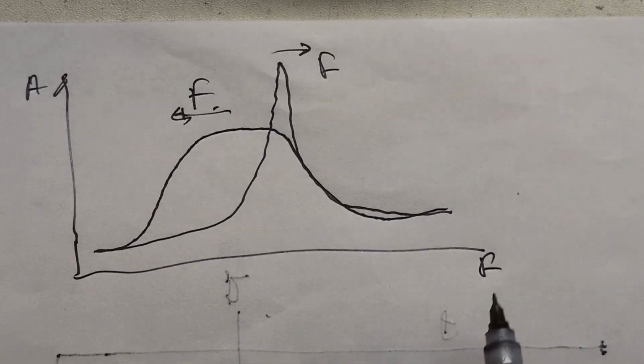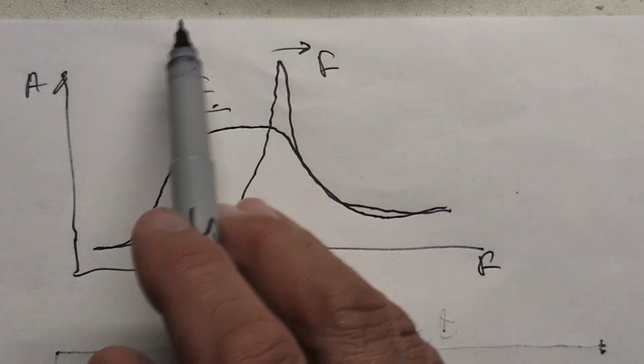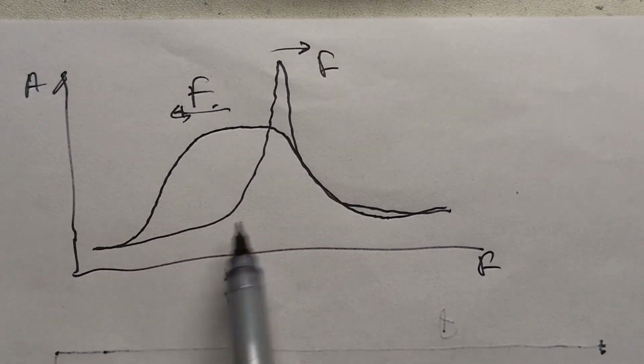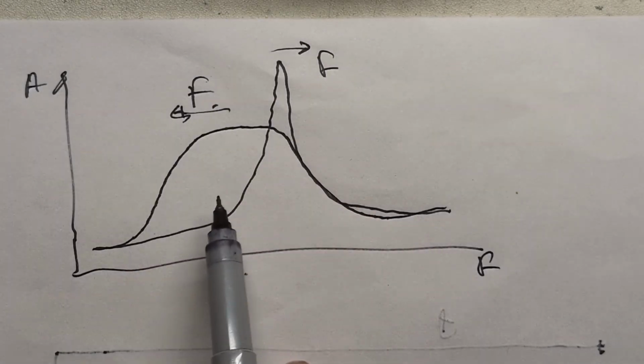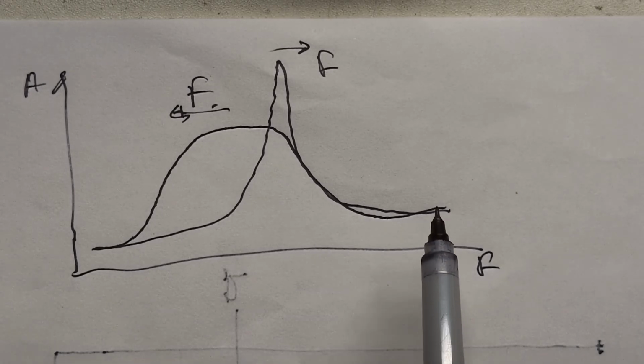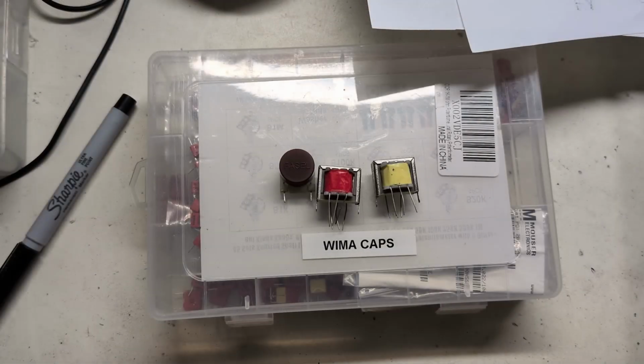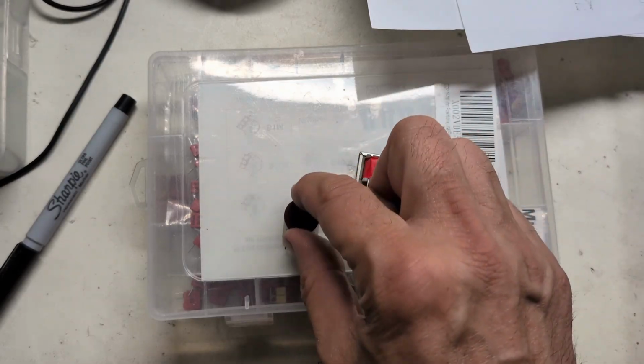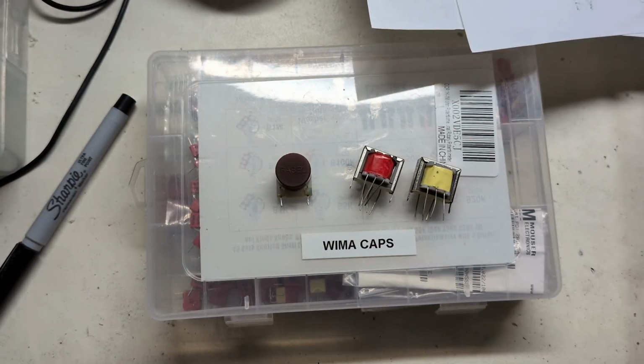So what we need to do is present this type of impedance variation, or this impedance profile, to the fuzz face, and also be able to use it with a buffer. Looking around the lab, I have a few inductors here. These are transformers, but it's a coil of wire, so it's an inductor, so we just use one side.